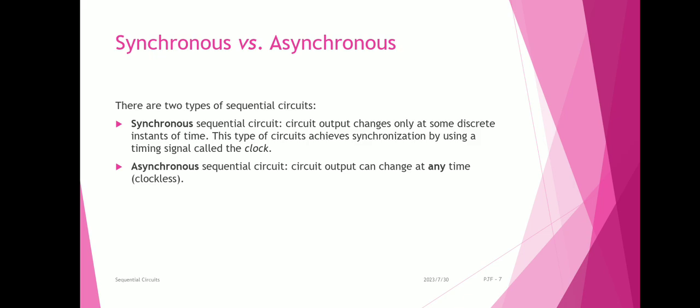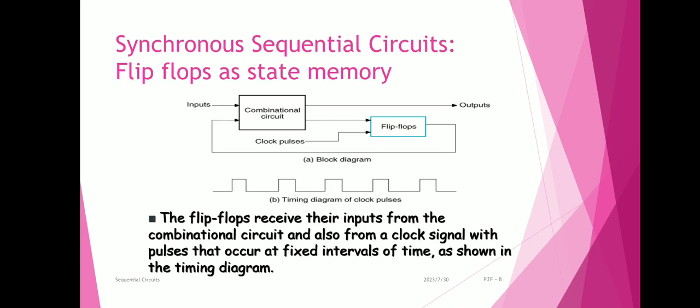In the case of asynchronous logic, it is more difficult to design and is subject to problems not encountered in synchronous design. The main problem is that digital memory elements are sensitive to the order in which their input signals arrive. If two signals arrive at a flip-flop or latch at almost the same time, the circuit can go into the wrong state depending on which signal gets there first. This is the major difference from synchronous circuits.